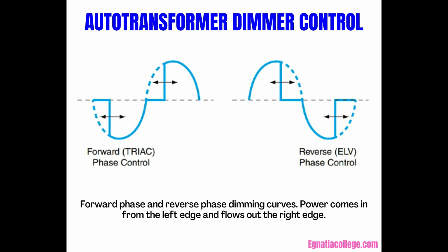Autotransformers require a special box that is furnished with the dimmer. They are common in commercial establishments, whereas the smaller solid-state dimmer is most commonly used in residential installations. Dimming traditionally involved what is called forward phase dimming, and the newer technology in use is reverse phase dimming. The distinction is important because of the LED lamps and drivers that are now being used around the world.